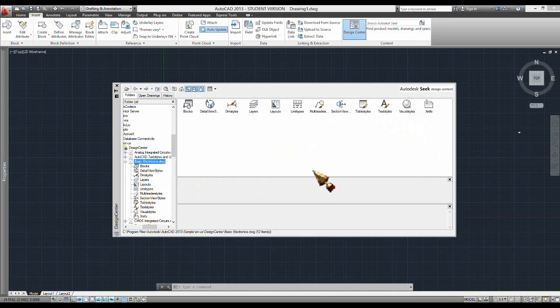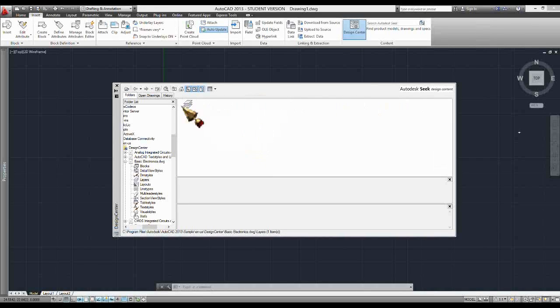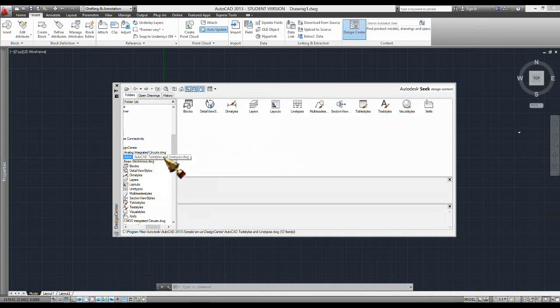But let's say you've begun drawing something, and you suddenly realize that this is not your default template. Rather than saying, oh, nuts, and starting over on your default template, you can go to your template, click on the layers, and pull the layers out. Now this particular one is only on 0 layer. But some other things you could do as well.